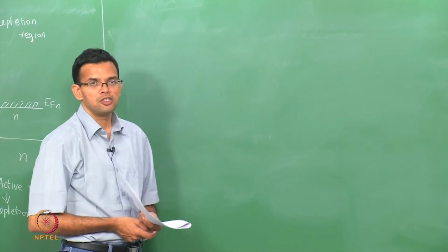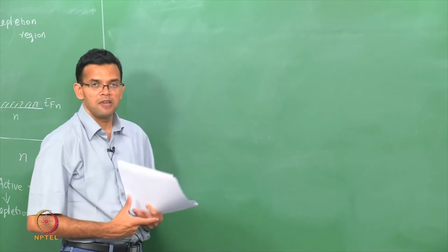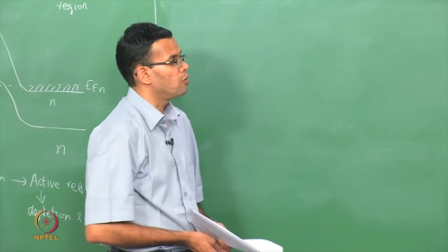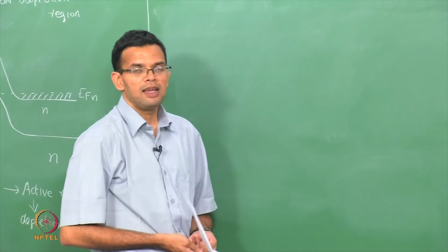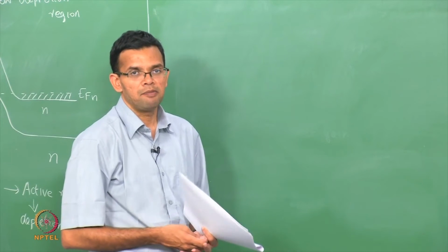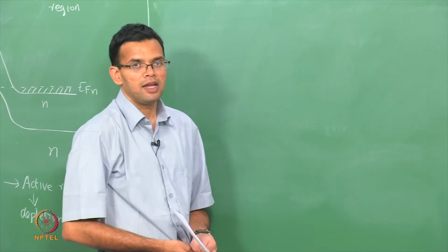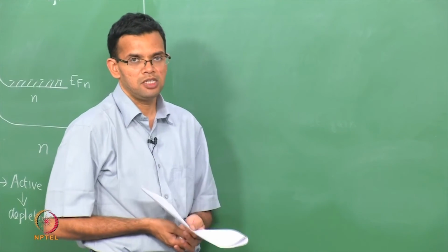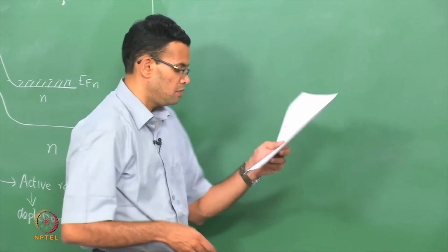The advantage of that in the case of waveguiding was that total internal reflection is also possible, but aluminum gallium arsenide also has a higher band gap than gallium arsenide. So, this helps to confine the carriers within the active region, which is the gallium arsenide region.